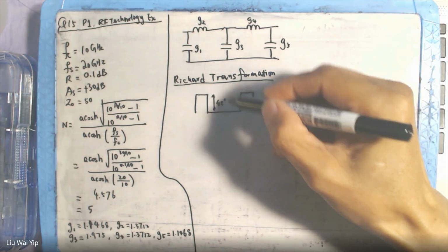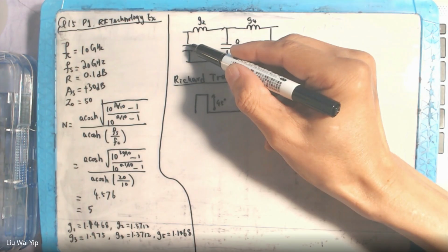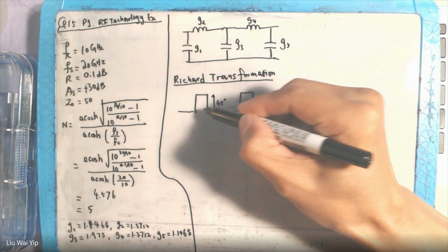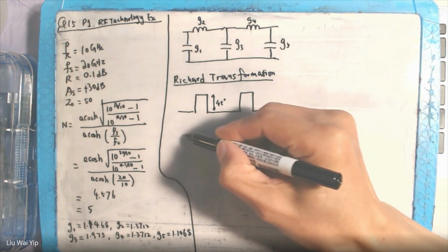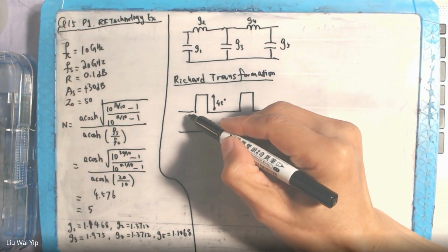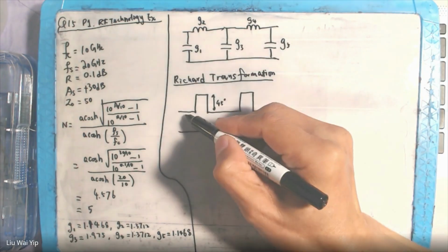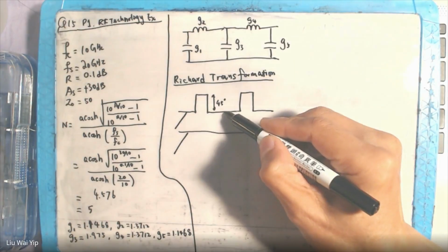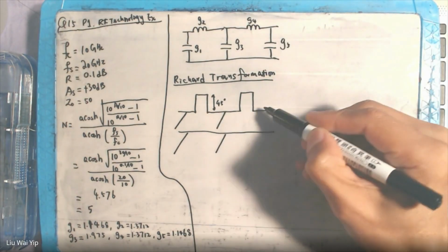And you are going to replace all the capacitors with open circuit stubs, here, here, and here.